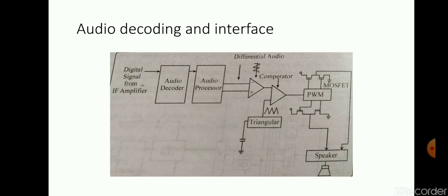Afterwards, power supply. It includes the AC to DC conversion to create the main power for the HDTV. Every functional block in the TV requires a particular power solution: DLP lamp, LCD bias, core and IO power for the main processor, memory as well as tuner and video or analog signal chains.